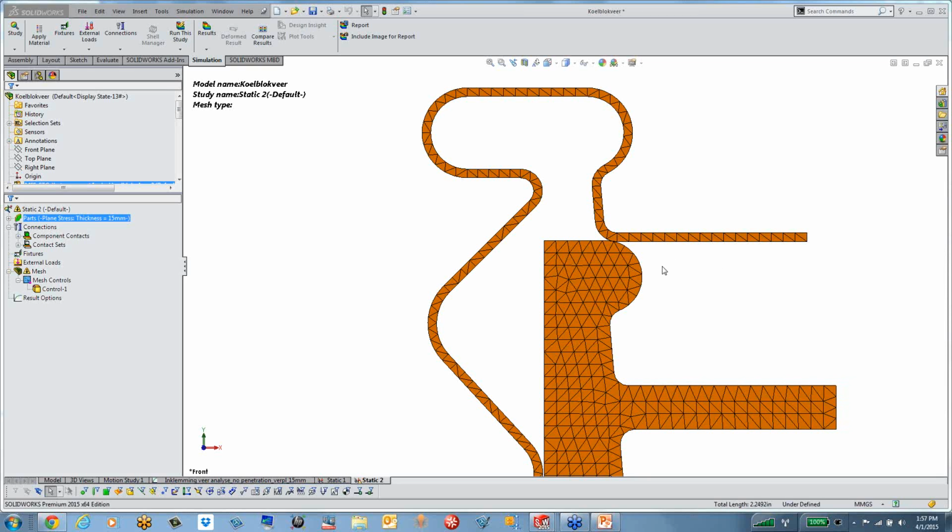So the next question is, how do you know when to use 2D or 3D analysis? Okay, so that's a great question. You can actually do 3D analysis pretty much on anything, right? So when it comes to doing 2D analysis, you can look at a couple of golden thumb rules, I would say. See if there's a constant cross section. Okay, so when I showed you plane stress, in plane stress, what happens is one dimension is much shorter than the other two. So the thickness in that case, in the assembly that I showed you, is much smaller than the width and the height. So when you're looking at cross sections like that, think about if there's a way to do a 2D analysis.